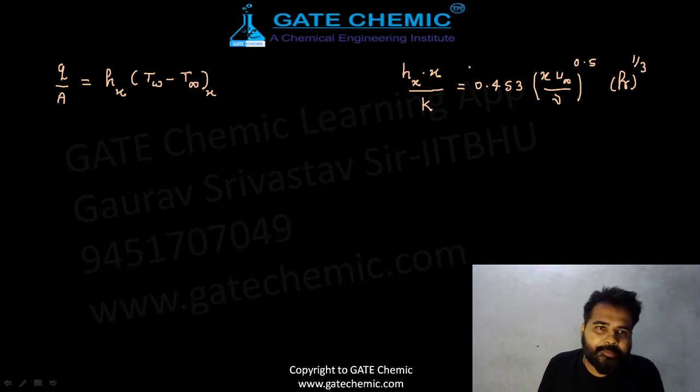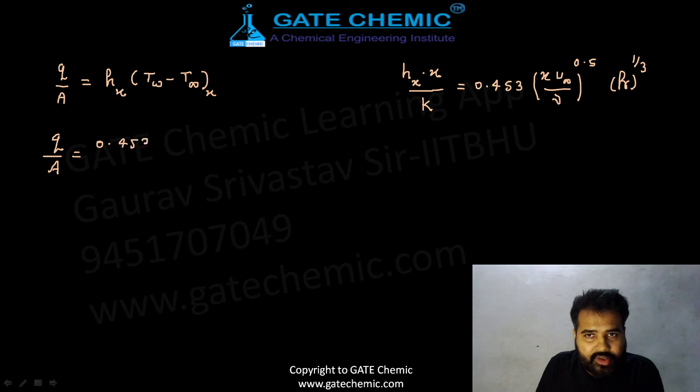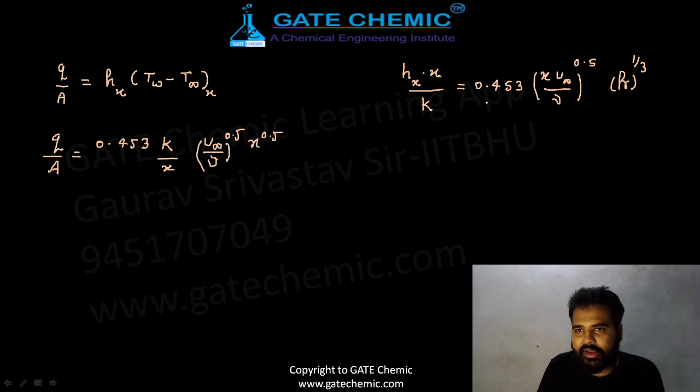Now you can see here that in place of this h_x, you can write this whole equation: 0.453 k by x, x is in denominator, and here u infinite by nu to the power 0.5 and x to the power 0.5. I'm taking this x outside of this bracket, and Prandtl number to the power 1 by 3, and then T_w minus T infinite local.